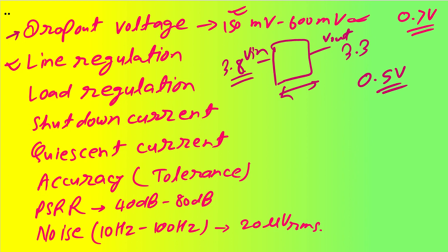What are the line regulation capabilities? Let's say it is like 2% or 1.5% or whatever it is. Load regulation is the same way, like let's say 0.5%. So lesser the better. Okay, if load regulation and line regulation both are small, or it can be given also in ampere by ampere rating. Okay, so if it is less, then it is good.